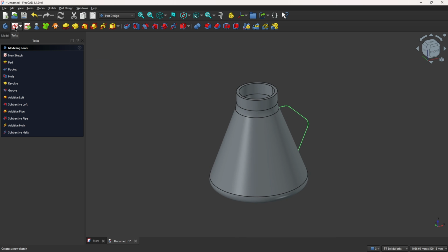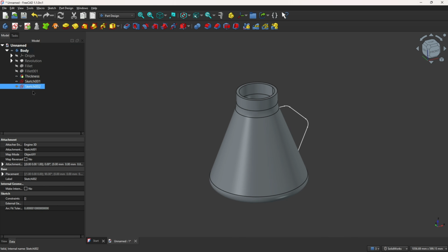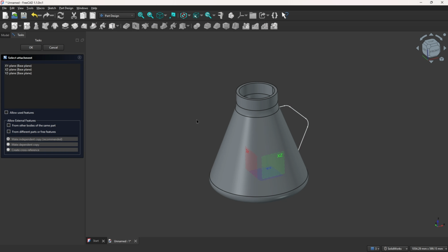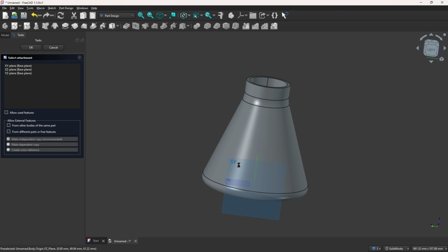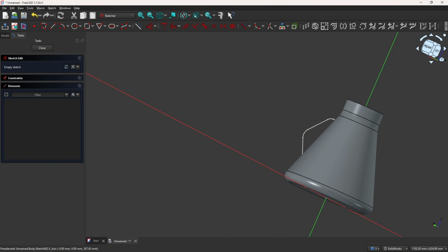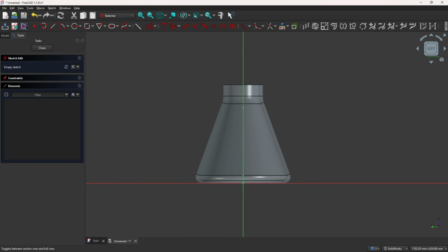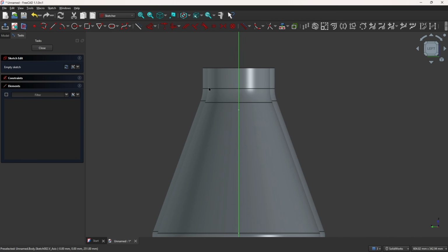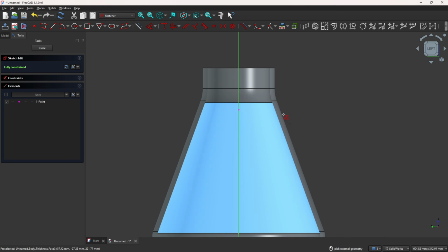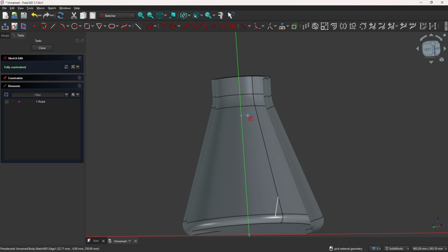And now go to create a sketch and select the, let me remove this sketch here. We needed to select the right plane to create a new sketch here. I will rotate this a little bit. Active the toggle section view. And here go to external projection and select this point here. This point is a line from the other sketch, okay?